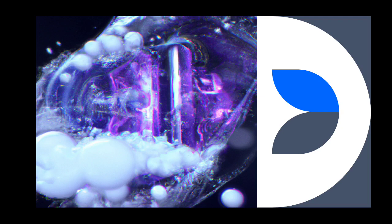So the point where the bubbles are forming is actually the low pressure area, the area where the pressure of the fluid is below its vapor pressure. So that is the reason those white bubbles which we are able to see in the picture are forming.